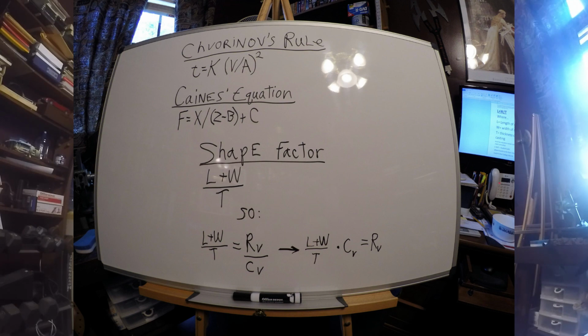When you have every bit of the water that overflows that first container caught, and you measure it, you'll find out how many cubic inches that might be, or how many cubic feet that might be, and there is your casting volume. Even then, that's a lot of work just to try and design a riser.